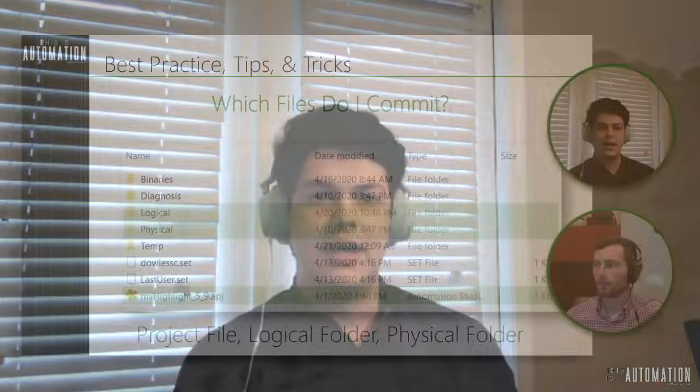Same with the diagnosis and temp folder, where the diagnosis has dynamically created trends, and the temp folder, say if you start a simulation within Automation Studio, contains specific files for that. So pretty much the key distinction is anything that you could basically replicate yourself in your local workspace, whether it be a binary or some sort of trend data or simulation data, that shouldn't be cluttering up your remote repository.